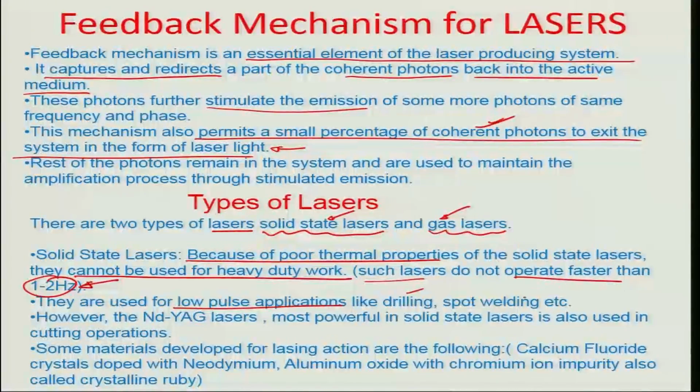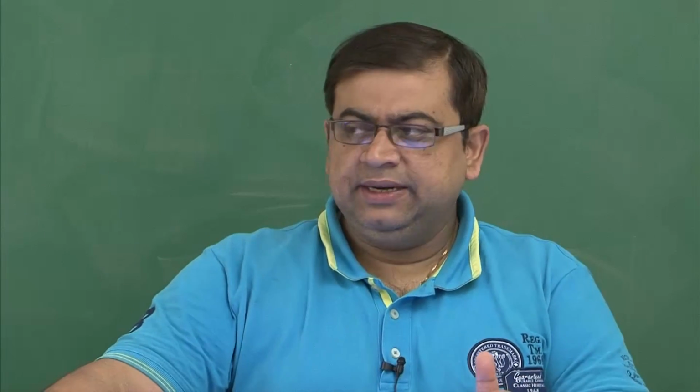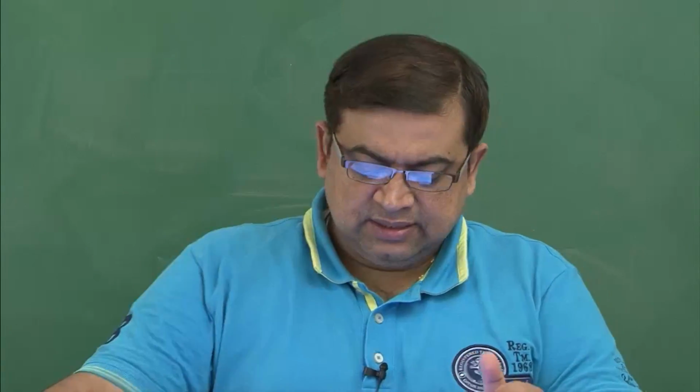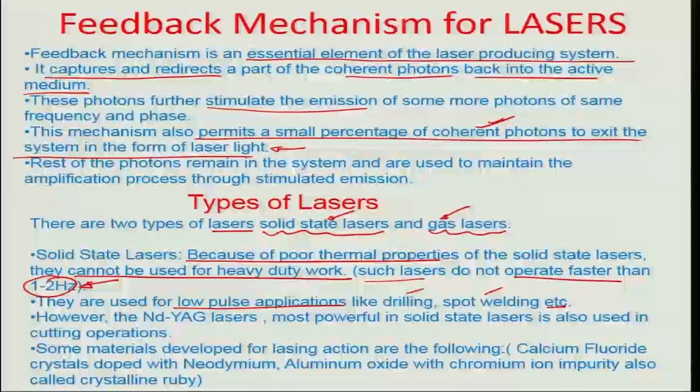You can have, let's say, drilling, spot welding, etc., where a portion of the material has to be intensely heated, so there is not really much of a pulsating kind of system needed. So there you can really use solid lasers quite a bit.